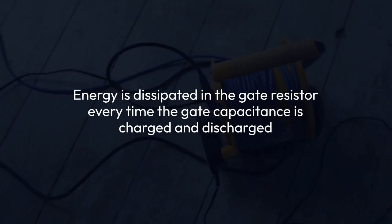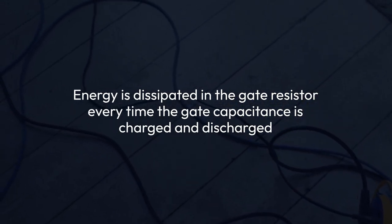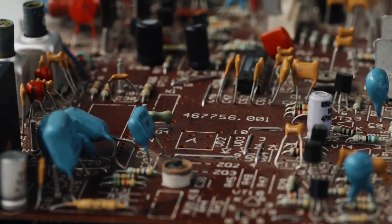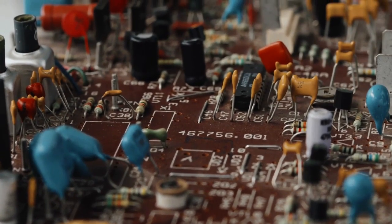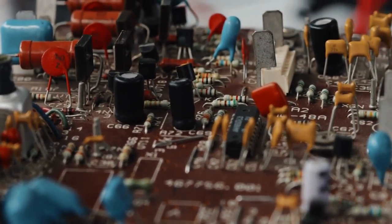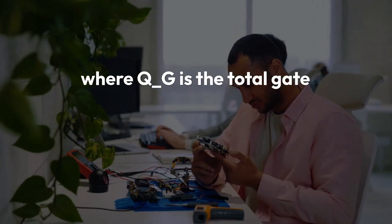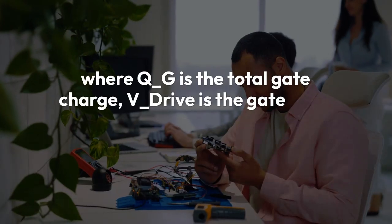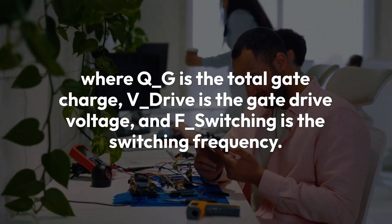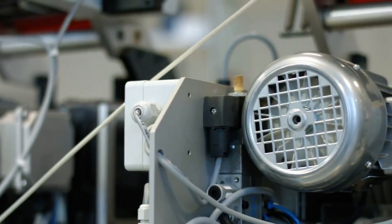Third, consider the power dissipation in the gate resistor. Every time the gate capacitance is charged and discharged, energy is dissipated in the gate resistor. A good approximation for the power dissipated in the gate resistor is P_dis equals Q_G times V_drive times F_switching, where Q_G is the total gate charge, V_drive is the gate drive voltage, and F_switching is the switching frequency. Ensure your chosen resistor has a power rating sufficient for this calculated dissipation, often requiring a larger wattage resistor than a typical signal resistor.